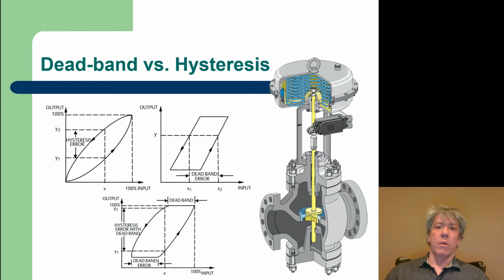And so when you try to get the valve to move initially, what happens is it doesn't move. It takes a certain minimum amount of force to overcome static friction. And then once it's moving, there's kinetic friction and things can move. But the primary behavior here is actually deadband, where when you're going from still, or going from one direction and reversing direction, you have some range of input, in other words, changes in the air pressure signal, over which there's no change in the output.